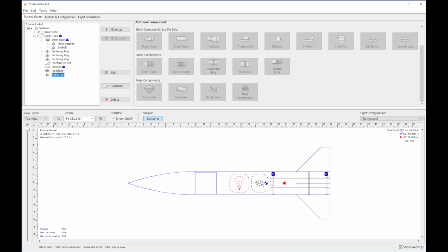That is the ratio of the distance between these two locations to the body tube diameter. So at about 18.5 and about 21, you're talking about 2.5 to 3, right? So you have about 2.5 inches from here to here and 3 inches here. So 2.5 divided by 3, you get 0.787, using whatever these actual values are. We want it to be 1.